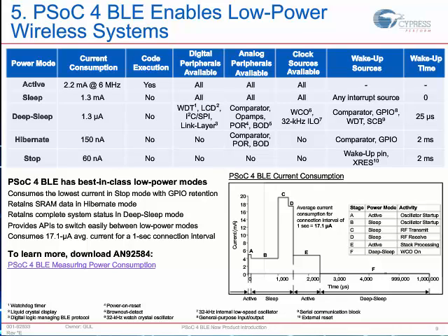where they're waiting for the next data to be refreshed, or they're waiting for the next call from the Bluetooth cell phone to provide it updated data. And so by exercising your low power modes and spending maximum amount of time on those, you can greatly impact your battery life. You can change your battery life on a product from 3 months to 12 months by intelligently and carefully using and exercising these low power modes as opposed to keeping your product in an all active mode at all times.